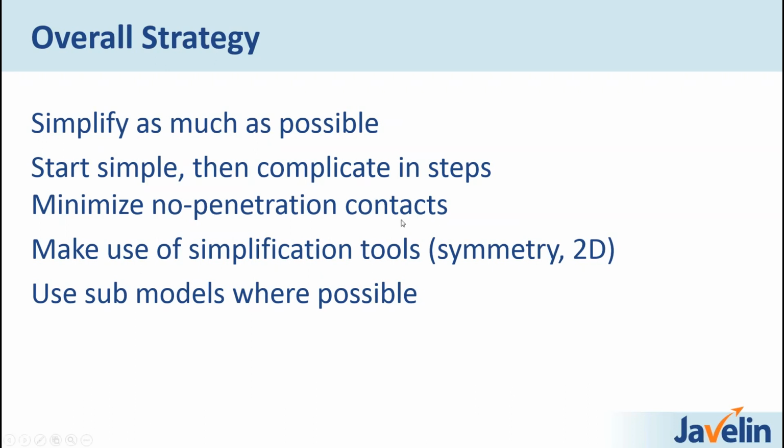The other thing we'll talk about is minimizing your no penetration contact. Now, obviously, that's not always possible to do. No penetration contact is necessary when you need contact stresses, and for a lot of other cases. But it's also going to be the largest time sink in terms of solving.